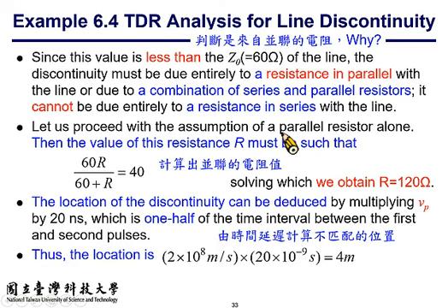So again, we observe that the round-trip time delay is 40 nanoseconds for the first reflected signal. So the one-way propagation delay is 20 nanoseconds. So use the delay time and the velocity of propagation, which is 2 times 10 to the 8th. We can find out the discontinuity shall appear at 4 meter. All right?